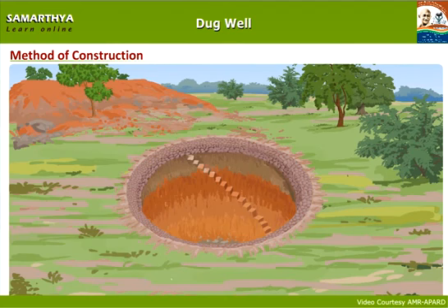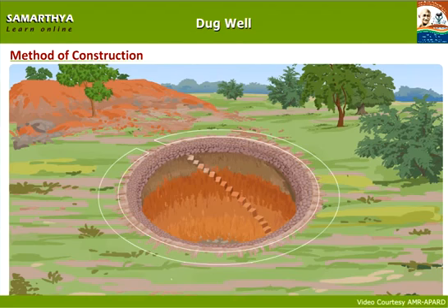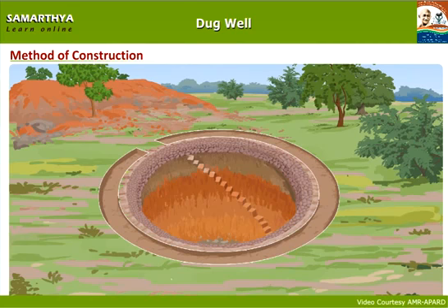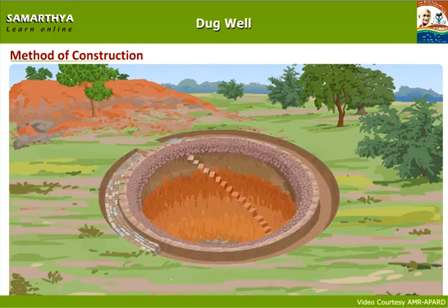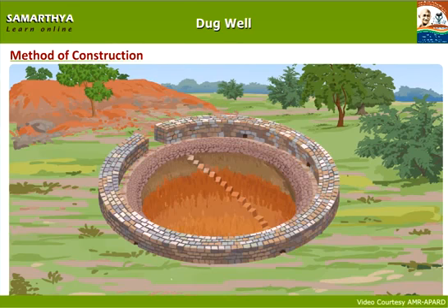In order to prevent runoff water and falling of small children into the well, leave a berm of 2 feet around the well, and a cement stone wall or cement concrete wall must be constructed with 1 meter height and 2 feet width.